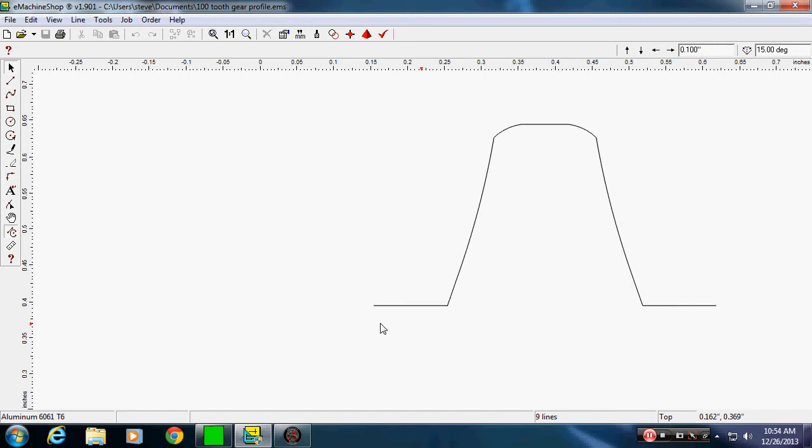You also, with a small cutter, could cut this shape into a thin piece of sheet metal to use as a gauge and actually manually cut this shape on your lathe and keep checking it with the sheet metal gauge you've cut out on the mill. So there's a lot of different uses once you have the actual profile.